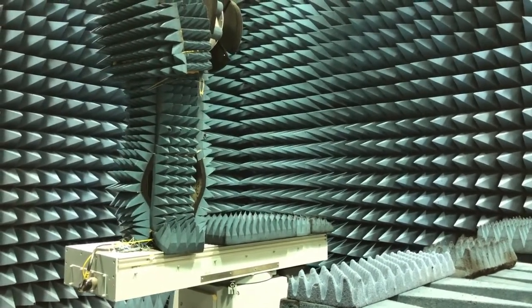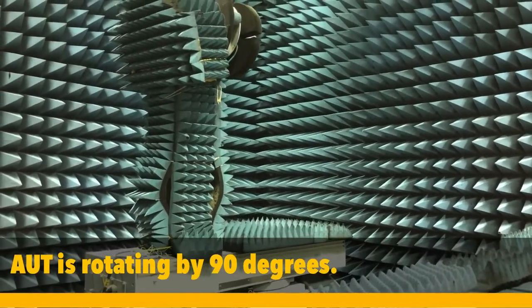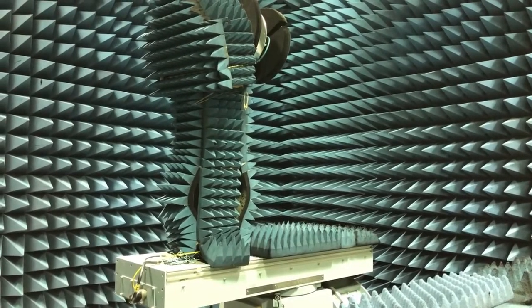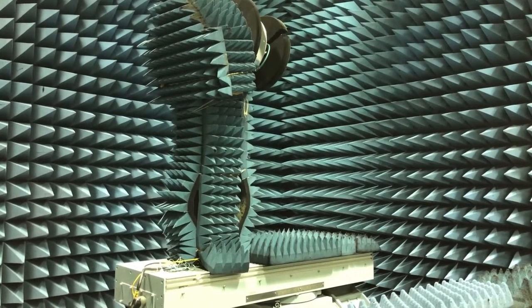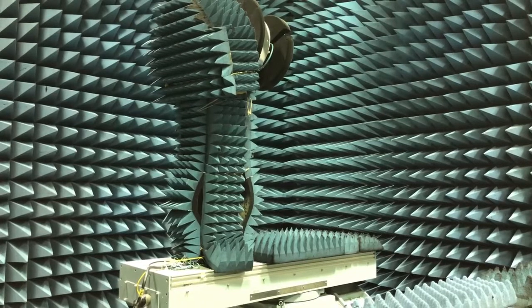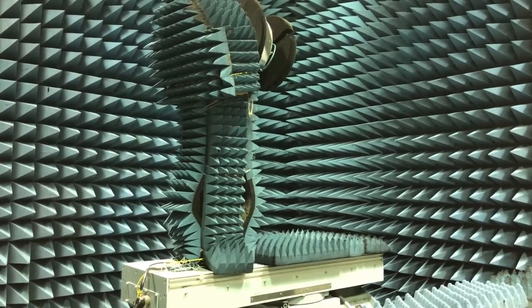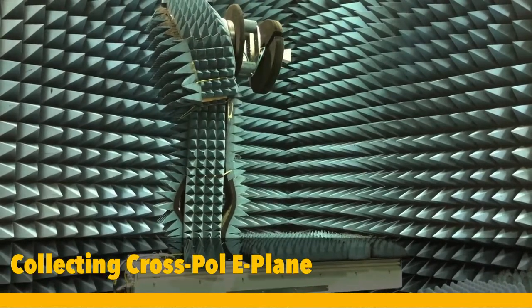Now the antenna under test should rotate. So you see the antenna under test is rotating 90°. So we go from H-plane to E-plane. Now, in terms of polarization, we are cross pole to E-plane. So when I'm performing the measurement, this is going to be cross pole E-plane.